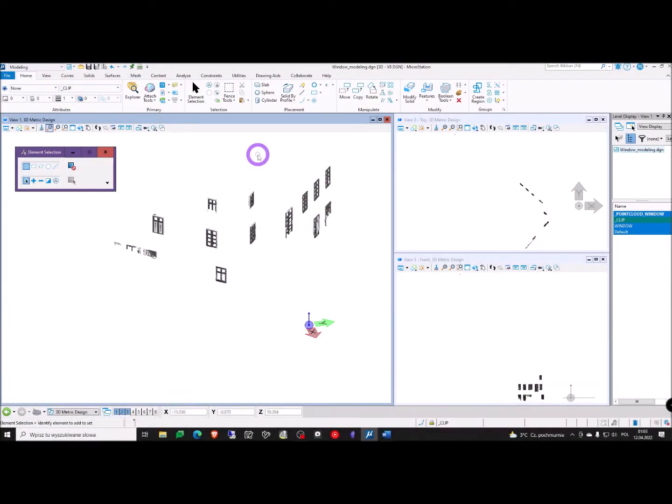When everything in the file is set up, the next stage will be the definition of the clip object that will allow us to limit the view to only a particular part of the model. To do that, we basically will be creating a basic slab and turning it into the clipping volume.